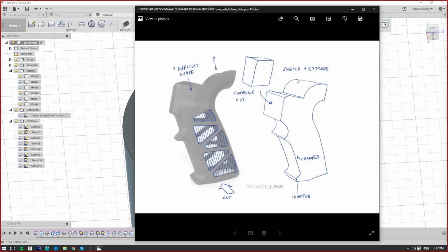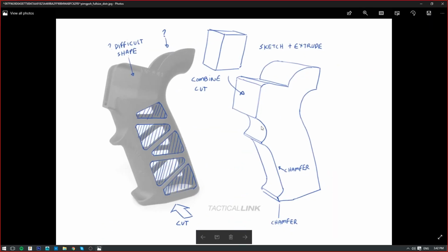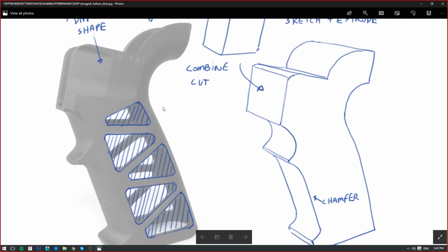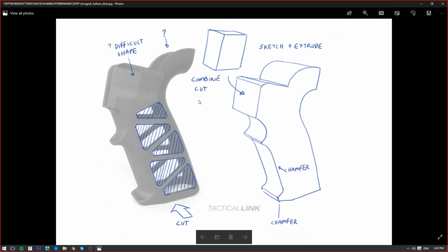So the last picture is actually what we touched upon in terms of the pistol grip, where in the image you can clearly see that if you sketch out this full shape, this looks more like there was another shape blended with it. If it looks like that, you should probably do it this way, which means as you're sketching your shape, this is where your shape will end, and then you take a box and cut it in and merge it with some fillets. A lot of times, because that's how it would have been machined and put together in the real world.